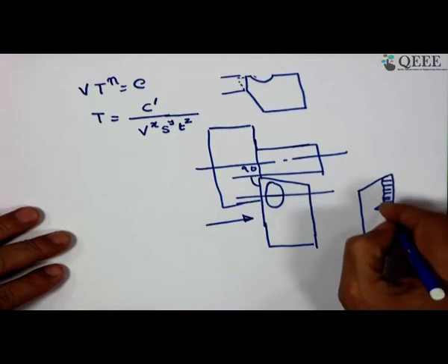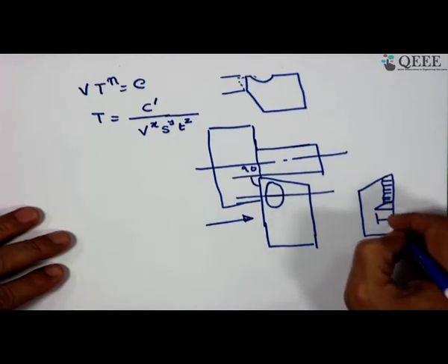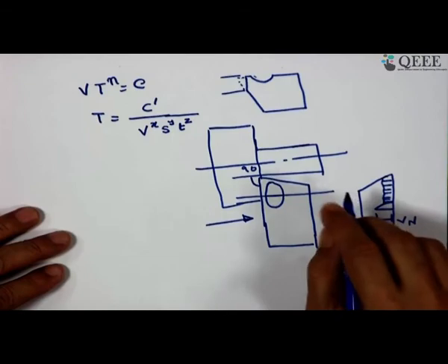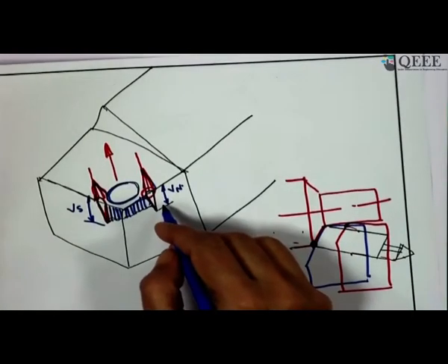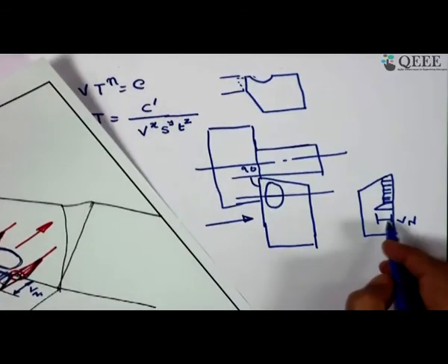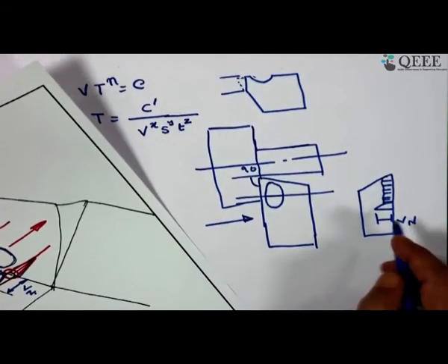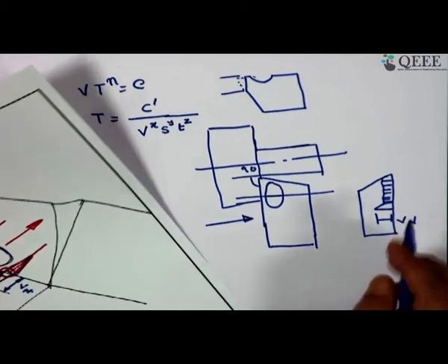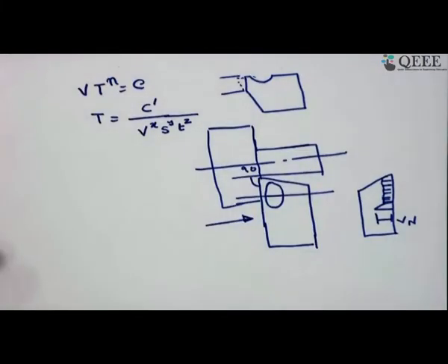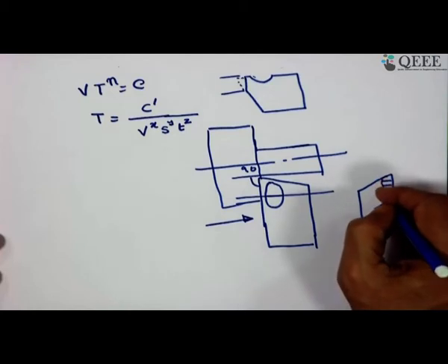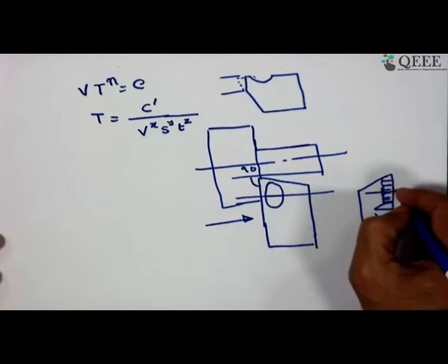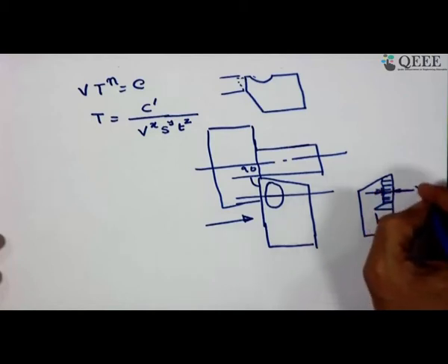The same notch you can represent by this diagram, which we see in the isometric representation as V n. The same V n you can see like this, and this you can really measure, and V b means the average of the flank wear over this zone, that we call the average flank wear, V b.